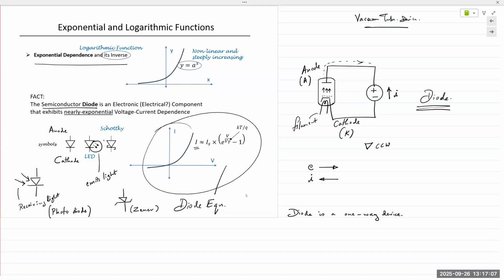All right. So if they have the regular diodes, depending on the numbers, 4001, 2, 3, 4, 5, 6, 7, 4001 can go up to 50 volts in reverse, whereas the 4007 can go up to 400 volts in reverse. You could technically take that 4007, stick it into a power outlet, and nothing will happen to it. It'll just behave like an open circuit.